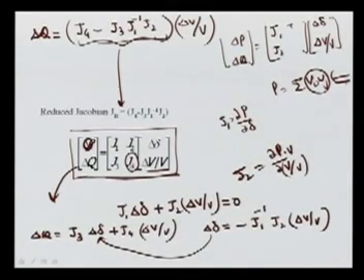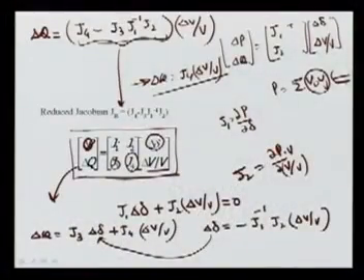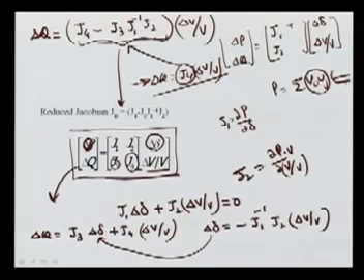Here we don't use this one, because if you are going for decoupling, normally this equation we ignore and say this is 0, and we can simply say delta Q is J4 change in V upon V. If the system is lightly loaded, this equation is valid. But in all cases, whether lightly loaded or heavily loaded, instead of J4 we can use JR, the reduced Jacobian. So this gives very good information for analysis of the voltage stability.